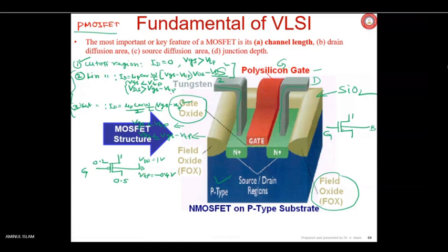Earlier values. So if I put that as 1 volt, this is say 0 volt. This must be source, this must be drain. In other words, what we have done is connected a battery. These electrons in the channel are getting repelled in this direction, and the positive terminal of the battery is attracting those electrons. Electrons are flowing in this way, and conventional current, of course, in this direction.